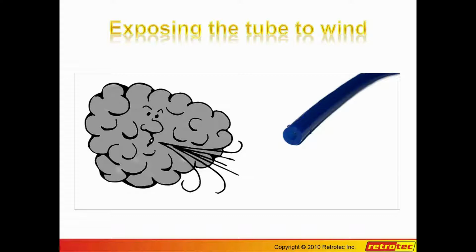And so the proof of the effectiveness of your pressure pickup system is whether or not you're getting fluctuations. So you may have to manipulate them to a certain extent for a certain period of time until you're happy with them. If the wind is not blowing, just throwing a tube outside will give you fine results as long as the fan is not blowing on the tube.